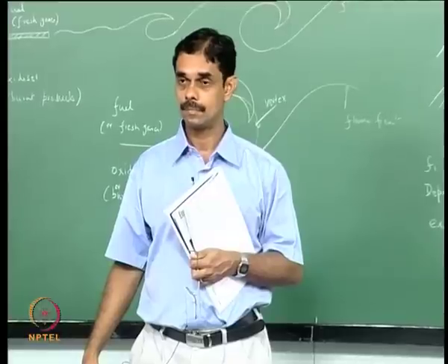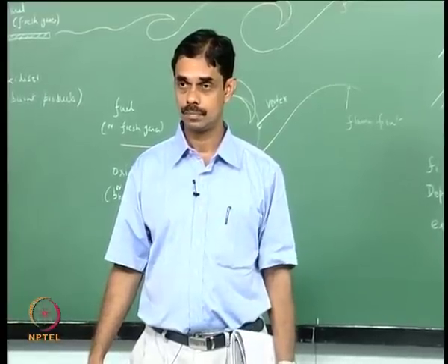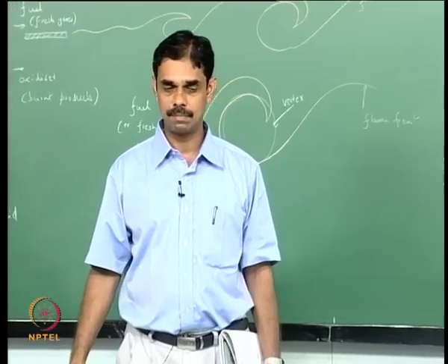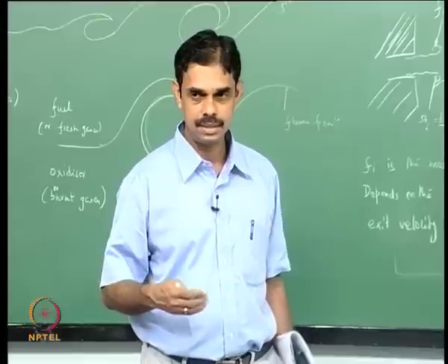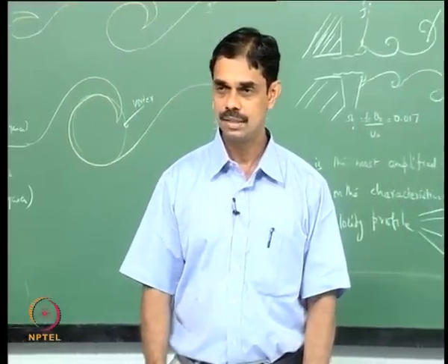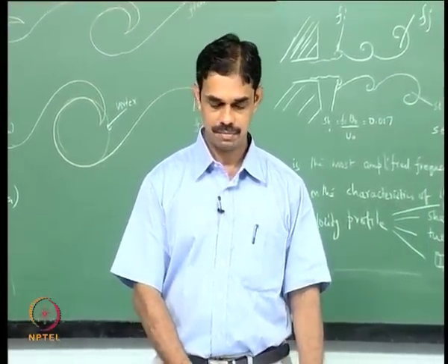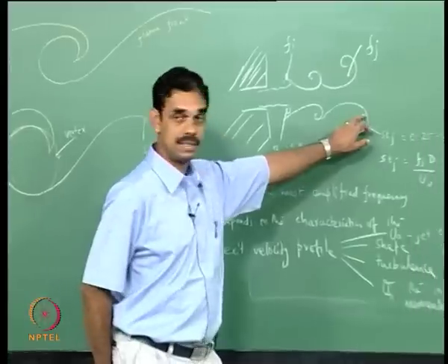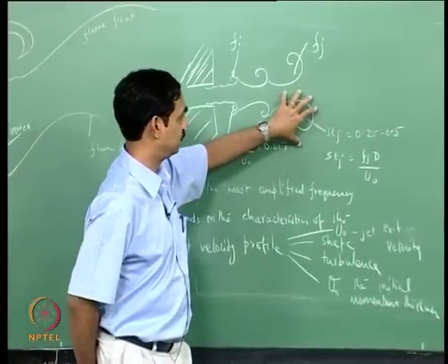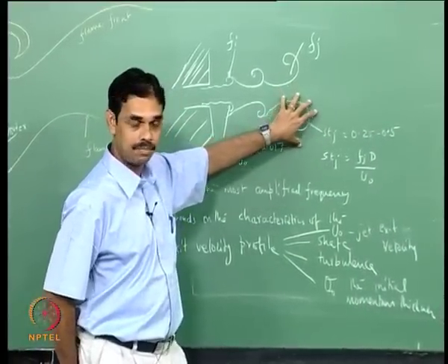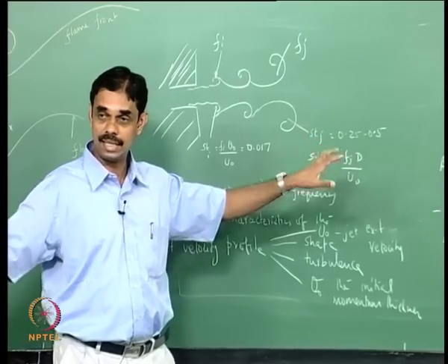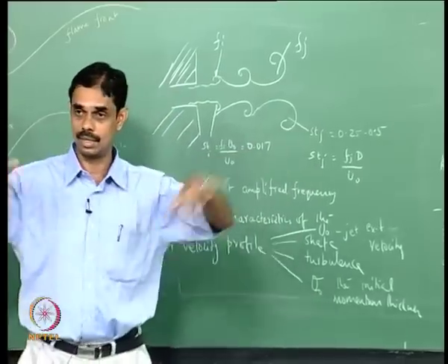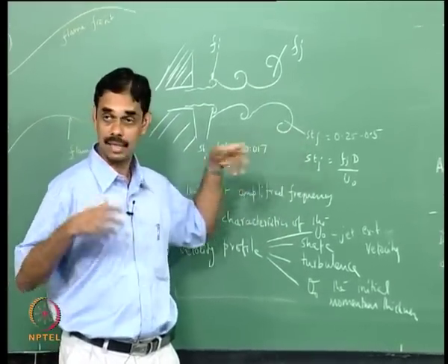So where do we use Strouhal number, like a particular Strouhal number means more mixing? You can't quite say that. Strouhal number is about receptivity. If you want to force with acoustic oscillations, and you force at this frequency, then you have coherent structures coming, and there is a preferred frequency at this Stj, and if you send the acoustic wave corresponding to that, this coherent structure will get very organized, and if you look at the spectra you will get a very sharp peak.